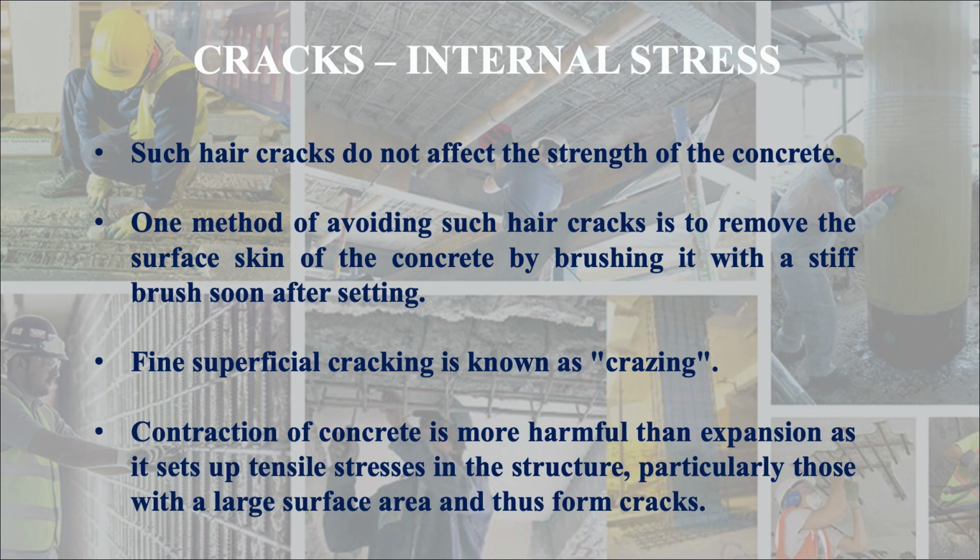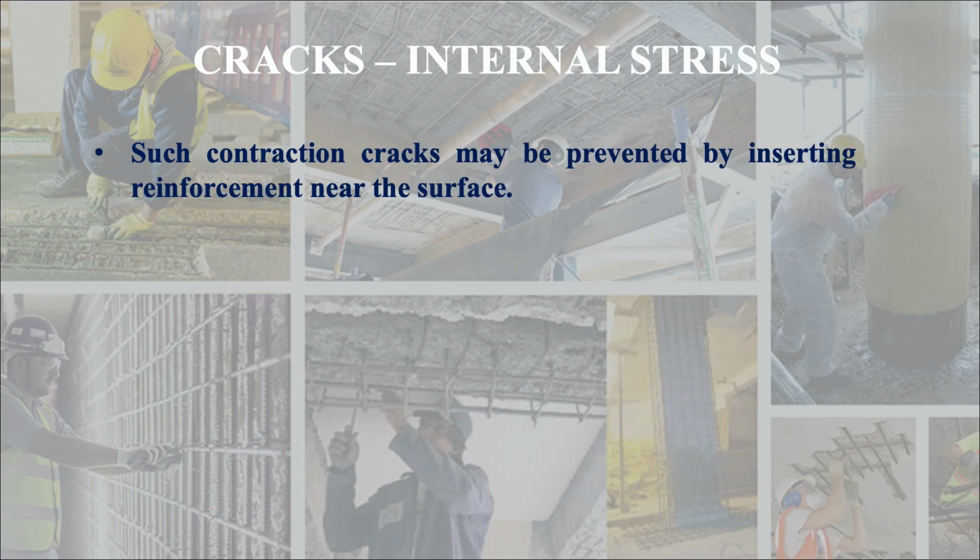Contraction of concrete is more harmful than expansion as it sets up tensile stresses in structures, particularly those with a large surface area, and thus forms cracks. Such contraction cracks may be prevented by inserting reinforcement near the surface.